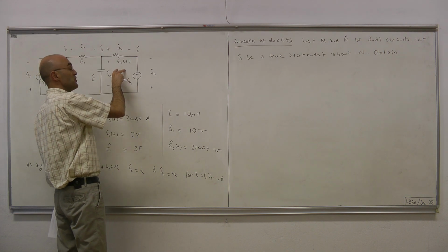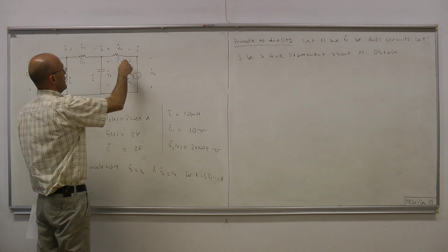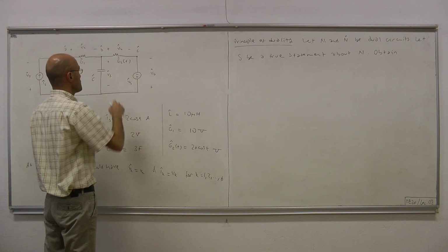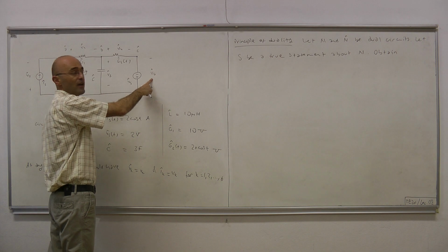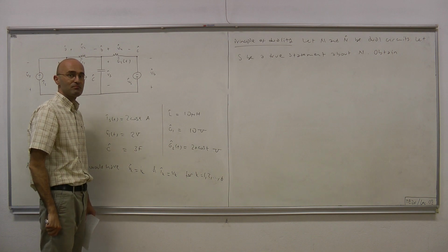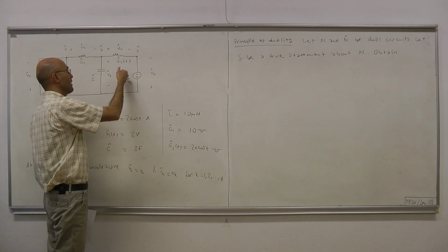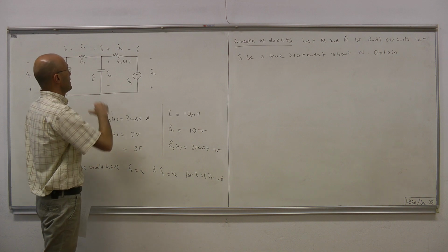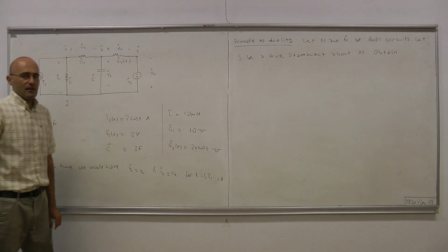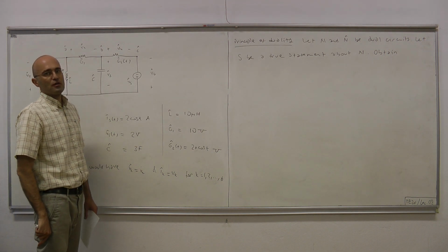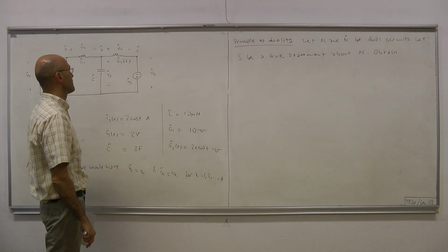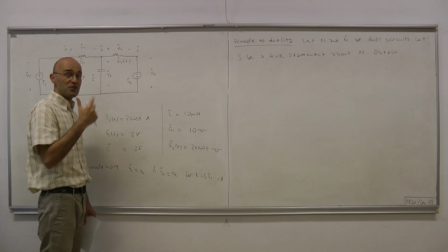suppose that this is the circuit which we dualize. For this mesh, there are 3 related voltages, V3, V4, V6, okay? And among all those 3 voltages that are related to that particular mesh, let's call it mesh M1, the one with the largest magnitude is V6 hat, and its value equals 12 volts, let's say. And so that's a statement. When we dualize that statement, it becomes the following, and it turns out that that statement is also true.